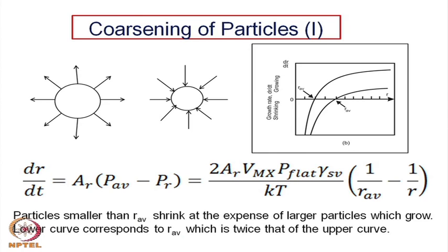That is not a satisfactory situation, because if there is a difference in grain sizes, then particularly the mechanical properties get deteriorated. Therefore, whenever we are trying to sinter a particular material, we need to process it in such a way, with the particle size, the agglomeration, and also the temperature rise controlled, that there is no abnormal grain growth.